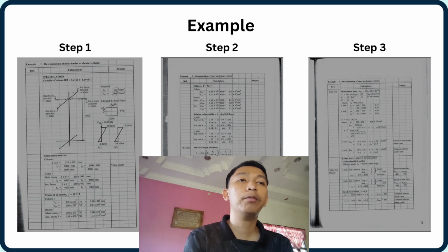we get 27.9, which is bigger than lambda z, which is 27.7, and the column is non-slender about the z-axis. For y-axis, lambda lim is 20 times 0.7 times 1.1 times 1.03 divided by 0.77 power of 1 over 2, and we get 18.1, much smaller than lambda y, which is 34.2, and it's shown that the column is slender about the y-axis.